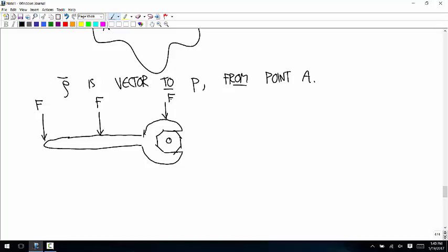it's easier to turn if you apply the force at the end than if you apply the force at the middle. And if you apply the force aiming through the axis of rotation, you can apply 1 billion pounds of force to that and it would never turn. All it would do is just rip the head of the bolt off. And so that's the idea of a moment. The moment tells you the tendency of the force you're applying to turn the object about that chosen axis, the about point.